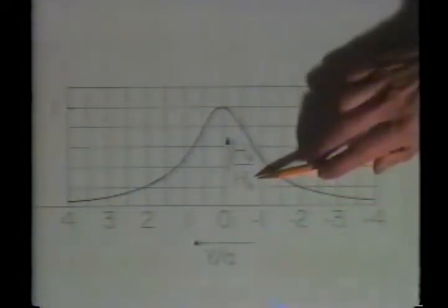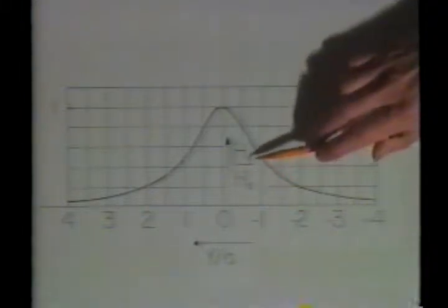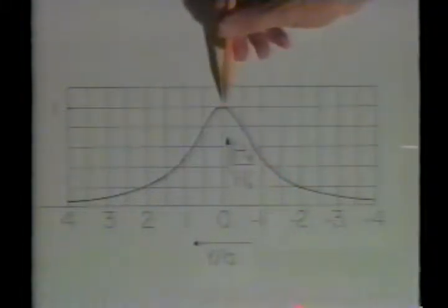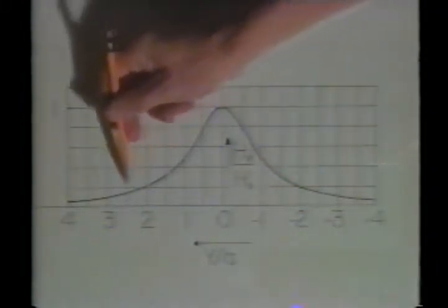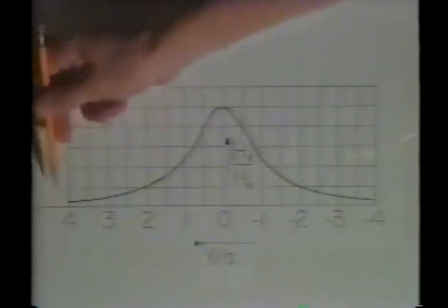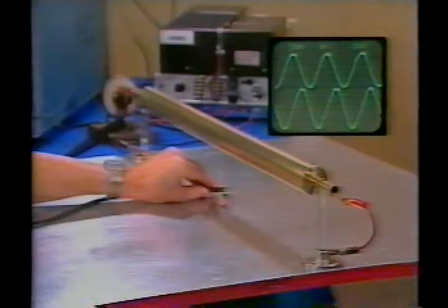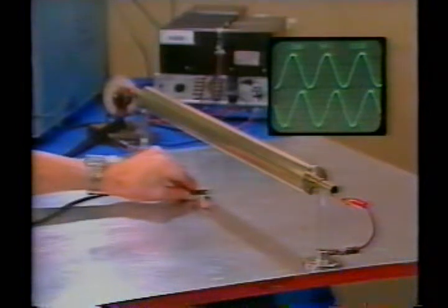So what we see is the distribution of surface current density returning in the sheet. At high frequency, the current distributes itself in the sheet in just such a way as to make the normal flux density near 0.